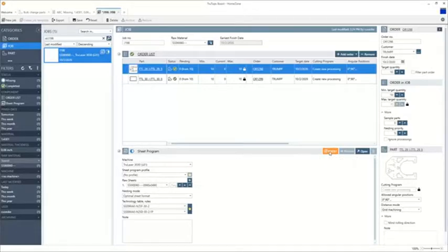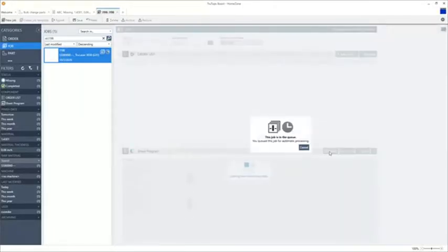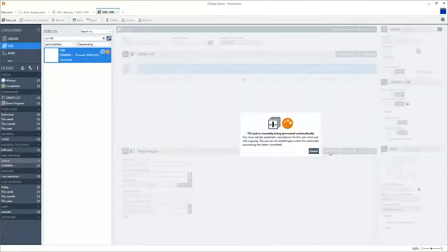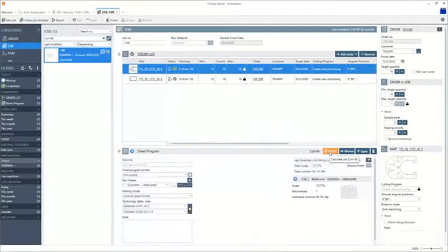And just like boosting the design or boosting the bending, boosting the job is creating automatic solutions. It's going to take those parts and quantities, nest them on the sheet size that I've selected with my profile and table parameters. So it's going to use my margins, my web width, and all those different parameters I mentioned before to automatically create a nest, automatically cut that nest, and then automatically sequence that nest. Once it's done, it will then generate the NC or the LST file for the machine and display the results.